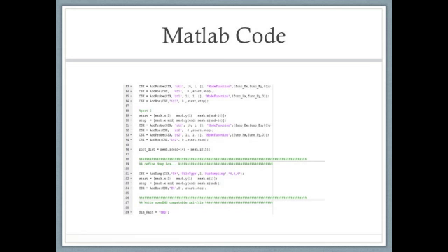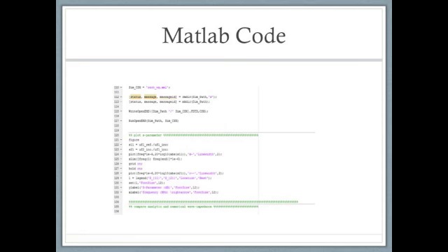The next part of the code is this. The first half of the code here creates the waveguide ports in my structure, which makes use of the electric and magnetic field functions I introduced earlier. The field dumps define the coordinates where the field is saved during simulation. This is the next part of my code. The first few lines of this code create the directory for simulation use, and write and run the OpenEMS code. The rest of the code just plots the S parameter in decibels versus the frequency in megahertz.